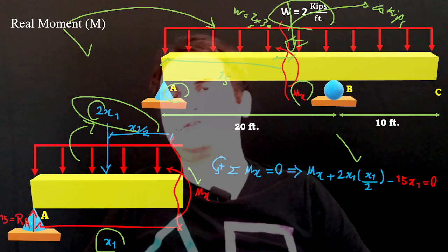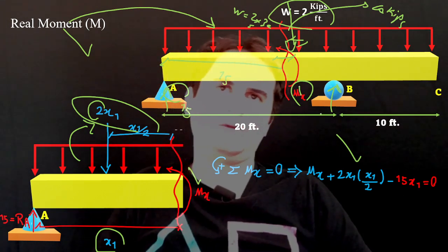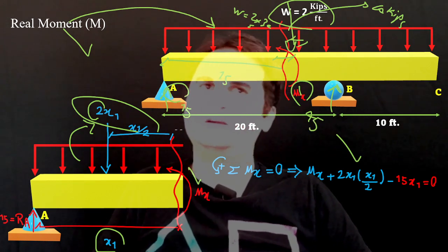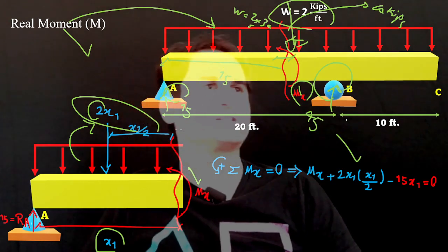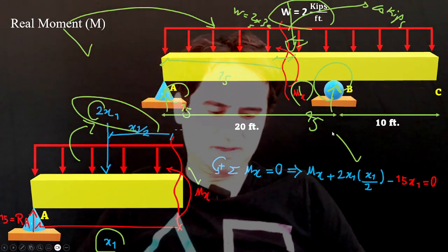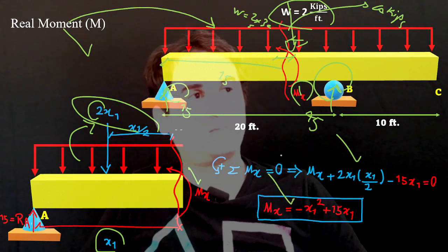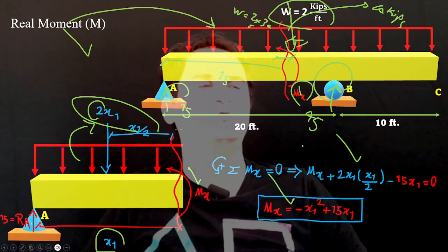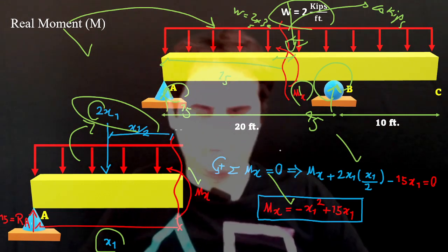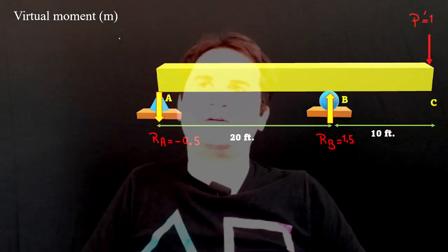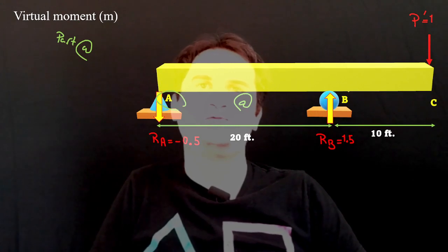So that's easily you can get what RA is, which I think is 15, and RB is 45. Definitely B is closer to the support, handling more share of axial force. So as soon as you have the equation for capital M, which remains the same in both structures because that's due to the real forces on the structure, it doesn't change from part A to part B.